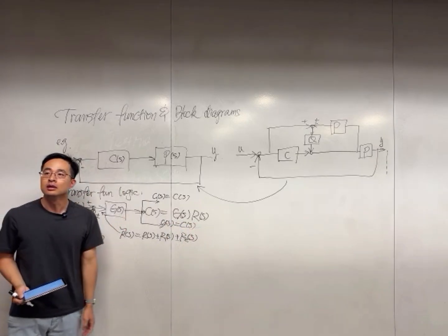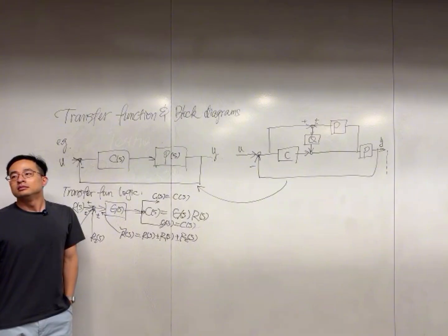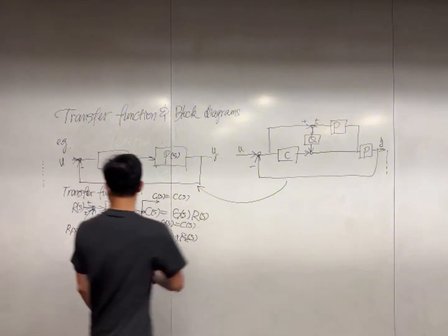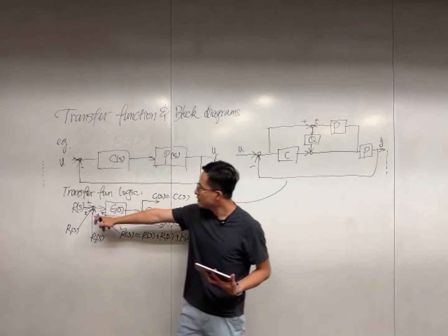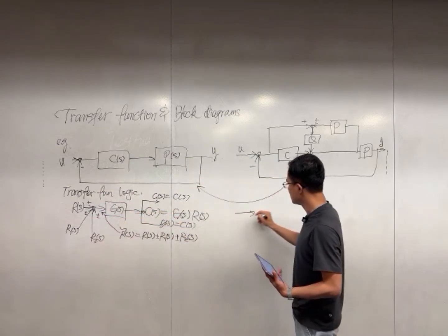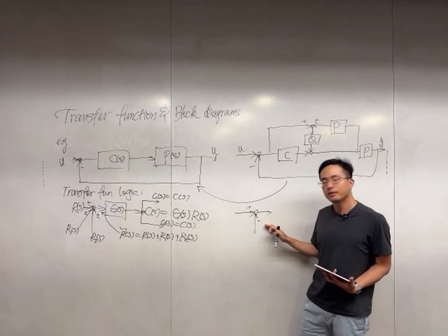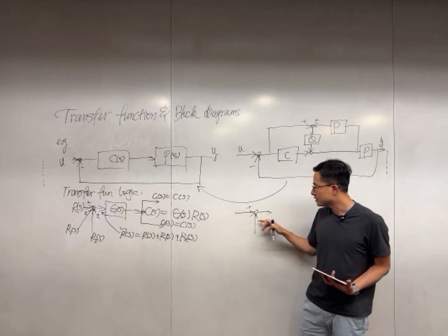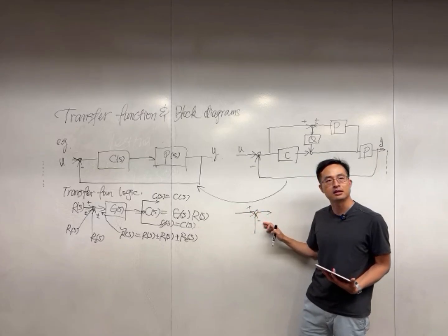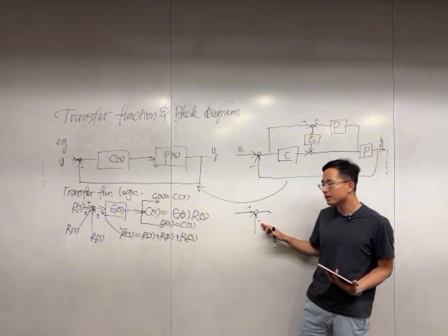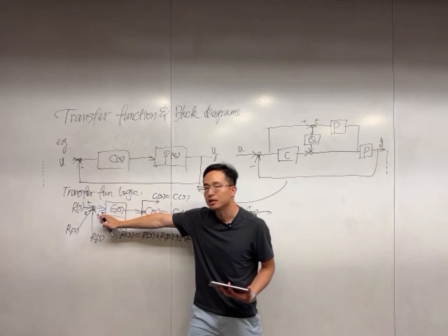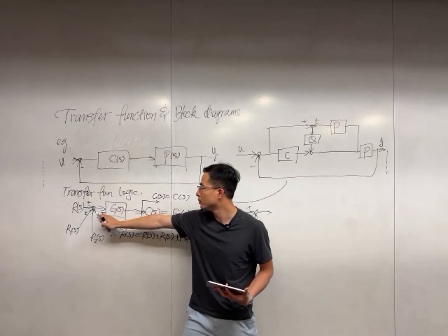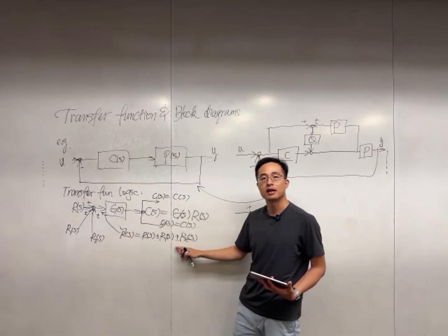Question? So again, whenever an arrow is going into a summing junction, it's going to be plus, and whenever it's leaving that summing junction, it's minus? So the summing junction, that's a good question. The summing junction can be written this way. The signs near the end of these arrows indicate the signs of these signals. Yes, if it is minus, then you write a minus. So the way that I use the notation here is it can be either plus or minus, and depending on whether it's plus or minus, the signs here will change.